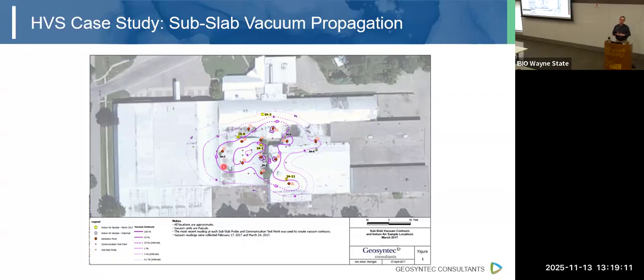The other thing is we've definitely had complaints from neighbors after we put in a mitigation system about the noise of the fans that we put in. So it's not just the technical nuts and bolts side of things, there are other considerations that come into play. For that, we suspected that noise might be an issue, so we were ready to go and put in some mufflers on those discharge stacks, and that knocked down the noise a lot.